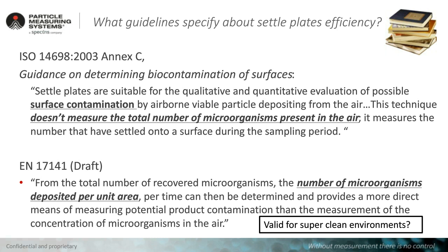It says that settle plates at the moment are a measure of the number of microorganisms that are deposited per unit area. It provides a more direct means of measuring potential product contamination than the measurement of the concentration of microorganisms in